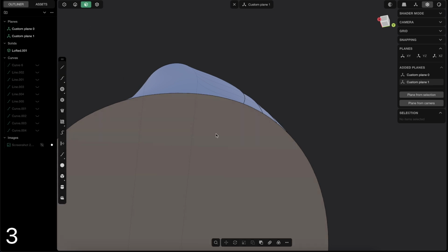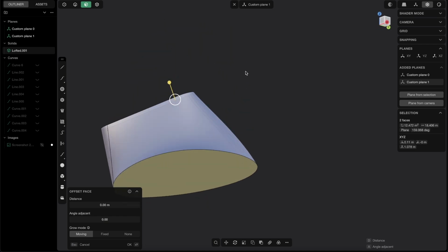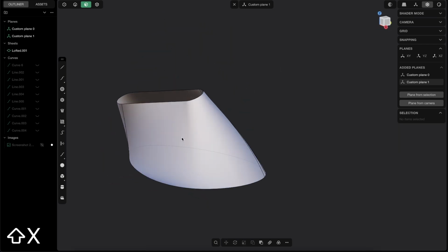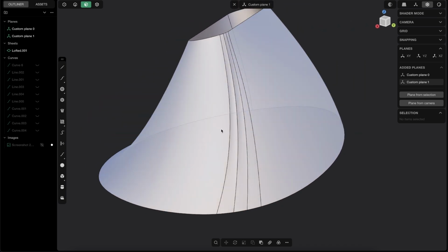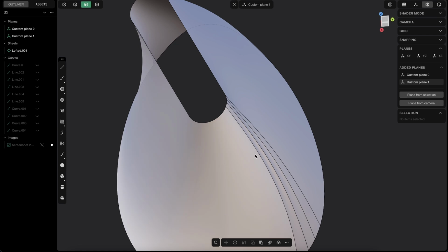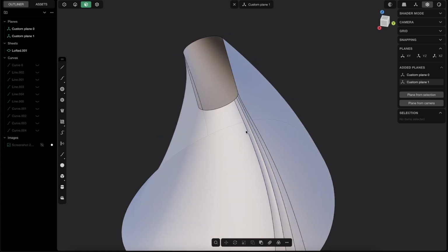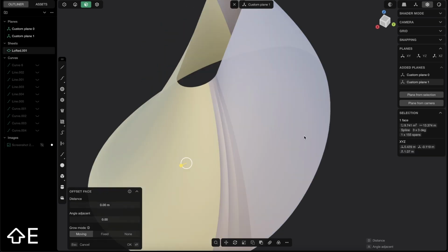And for that, we first press 3 for face mode, delete those 2 faces here, Shift X, because we now need a sheet. We can't work with a solid. And first of all, you create that, of course. So literally just pause the video and do all of those waves. It will go into your muscle memory, and then you will know for your whole life how to do this kind of shape.